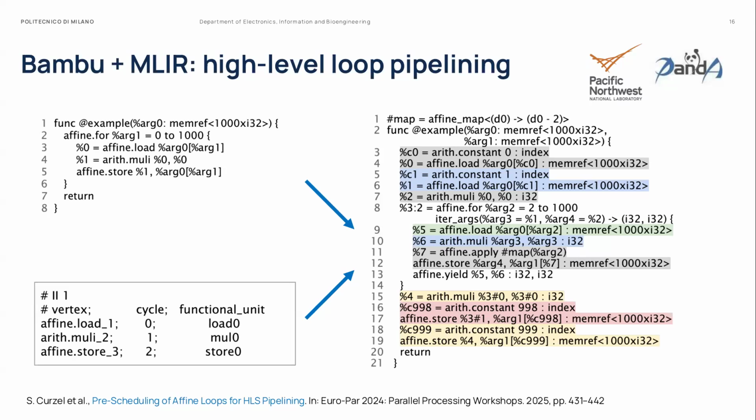Yes. So when you describe something in TensorFlow and then you ask the compiler, I don't remember the name, you can generate the GPU code or CPU code. We take the CPU code version and we synthesize that one. Because when it generates GPU code, I think it already generates the binary or the instructions for the NVIDIA GPUs or something. So those are no use to us, but the MLIR version for CPU can get down to LLVM-IR and be synthesized.